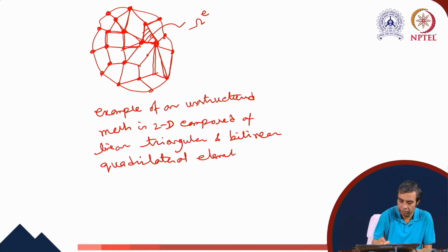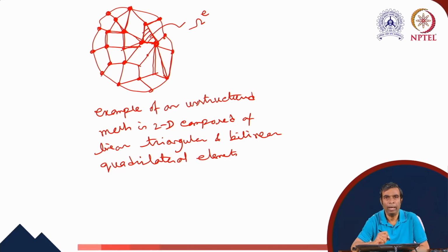In this picture, the nodes which are located at the boundary are the boundary nodes, and the nodes which are inside are the internal nodes. When we do the FEM formulation, at the beginning we identify the nodes which are located at the boundary and which type of boundary condition will be applied on those nodes. The set of essential boundary nodes is given by the symbol eta g.